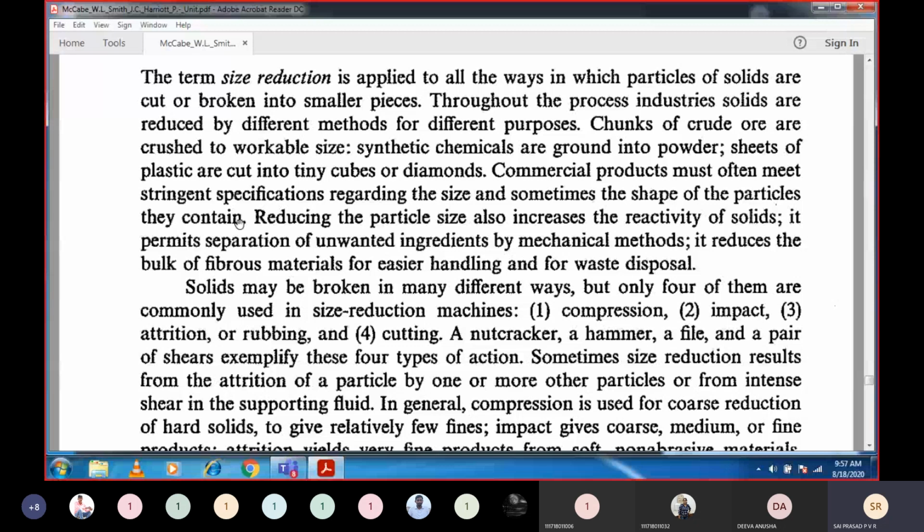So it all depends upon the consumer, and the consumer will purchase only commercial products. Hence commercial product size requirements are stringent, meaning strict, and we are supposed to follow them. Once they say -200 mesh, you can go for -200 mesh, and in some cases beyond that is accepted. But stringent means -200 is a must. At the same time, the shape of the particles is also very important. As long as you crush the particles, you will definitely have rounded particles only, not intricate shapes.